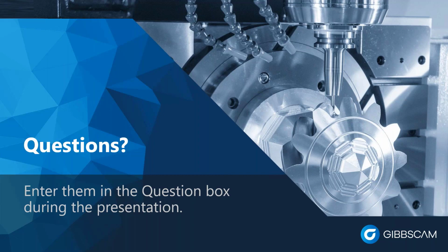Absolutely, yeah, you can. In the tool axis control, you can put a lead on the tool, and I didn't really display that. It would have been suitable perhaps in the first toolpath option I created, and that way you're not machining at the tip of the tool, but by rotating the axis of the tool relative to the surface you're cutting, then you're cutting out on the radius of the ball or your end mill, and thus getting better surface footage. All right, agreed.